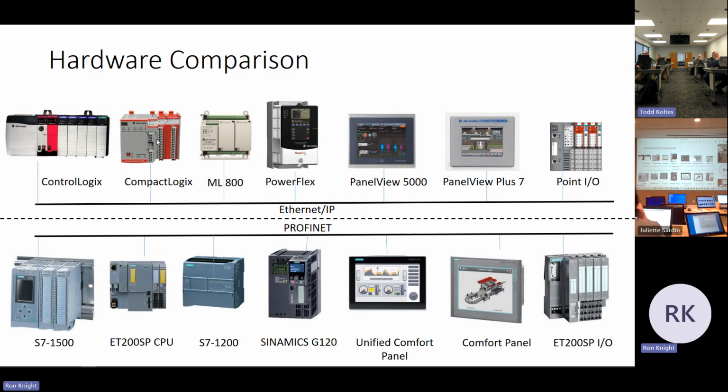Compact Logix is an interesting PLC. On the one hand, you can do very small machines, very low-end Compact Logix with some onboard I/O, all the way up to very large processes. I mean, this Compact Logix has the same CPU in it as an L8 ControlLogix. It's also very expensive. So it really depends on what Compact Logix we're talking about here as to what you compare on the Siemens side. You know, it could still be the 1500. That's a good look at that ET200SP CPU that we talked about.